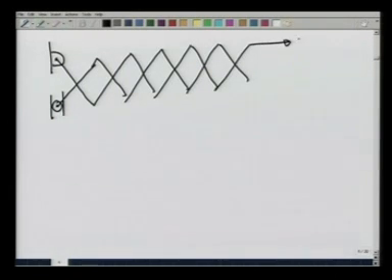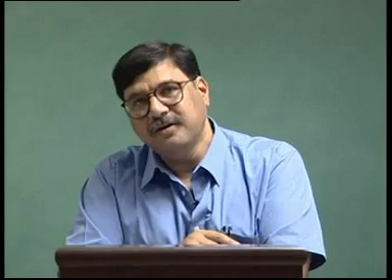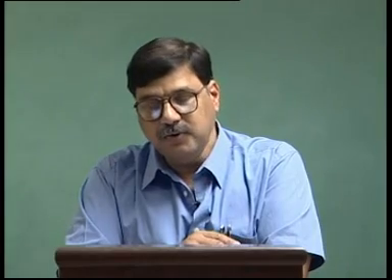And I apply a force here. Each link, each of these bars, has mass m and length 2b, and I want to calculate the force F to keep this whole thing in equilibrium. You see, if we go the conventional way, I will have to build up the solution step by step. With the method of virtual work, we will be able to do it in a much easier manner.